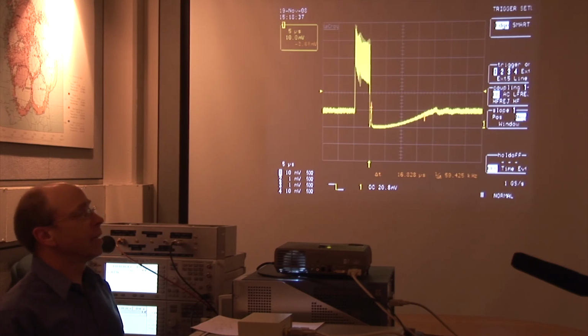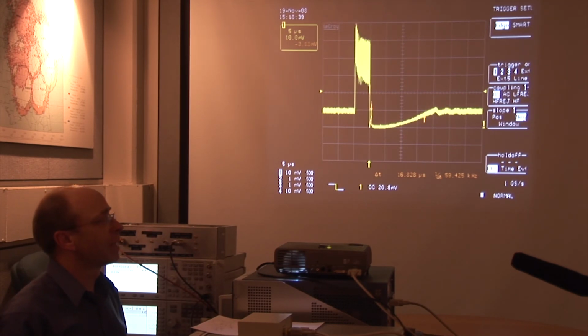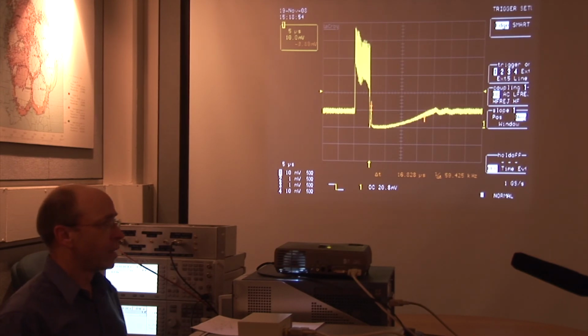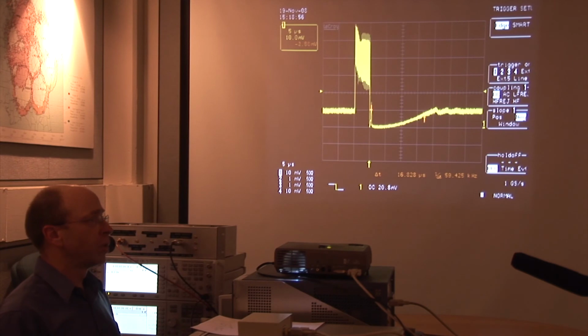Although I've never seen that happen, I could imagine it happening if a broadcast source were somewhere in the area. I know what I would do. I would disconnect the receiver's antenna from the rest of the system. I would look at the output of the low noise amplifier of that receiver and measure it and make a note of what it is.